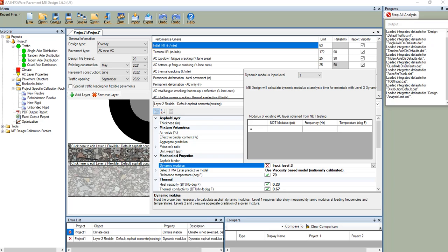We carry a truck, drop a load on the pavement surface, measure the deflection at various radial distances, and we back calculate using software. So you need to determine this. Say I am assuming here 500,000, which is a very high number. Say at frequency 10, and at that time my temperature was 65 degrees Celsius. I'm just guessing something. Is it 500 or 50?